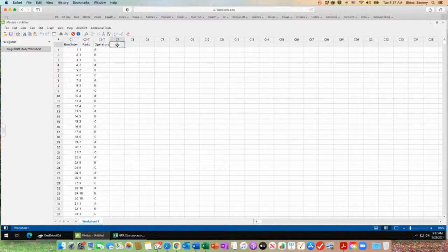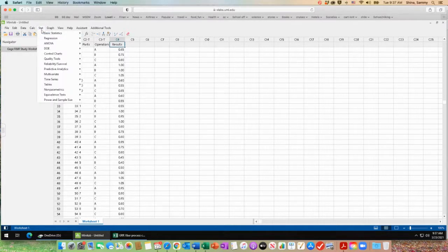So all I have to do is go here. Notice I go right below C4 because you can preserve the title, and I paste it. So these are the results, which is the title, and we see that we indeed pasted 60 measurements. So now we can do the work. We go back to Stat. Now it made the table for us. We measure the 60 parts, and then we enter the 60 part measurements in that column. Of course, you don't want to confuse them. Make sure it's the right part with the right operator and the right measurement. So don't make any mistakes on that.